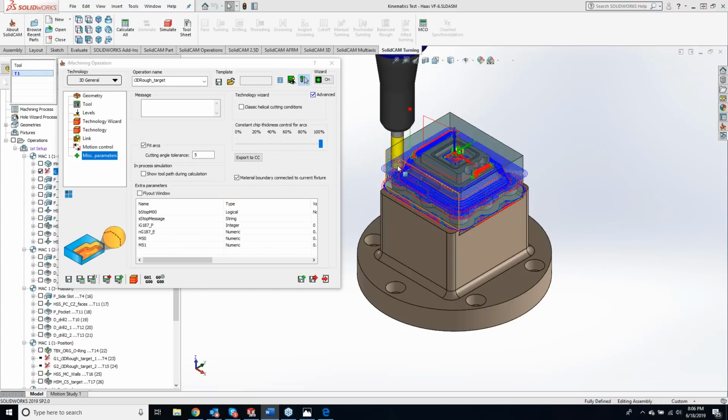By turning on the fit arcs, what this will do is take the cutting tolerance that's used in each section of the iMachining toolpath that falls between the specified tolerance. So what it's saying here is if I open up this tolerance, I can actually reduce the amount of G code in the machine. Or actually, no, I'm sorry, I got that reversed. A small tolerance can greatly reduce the amount of G code that is being generated.